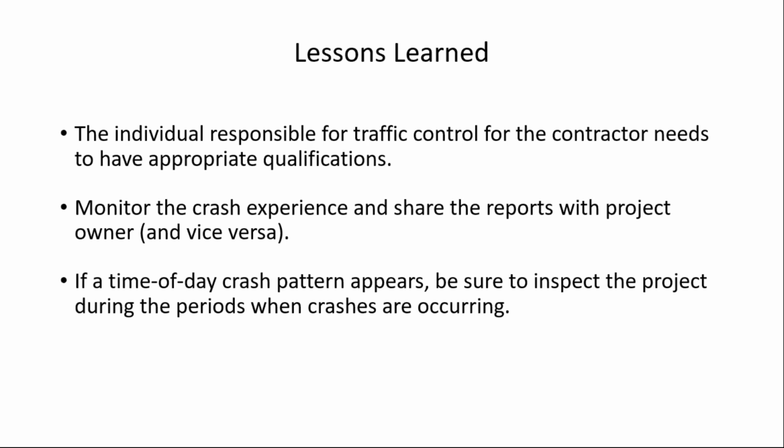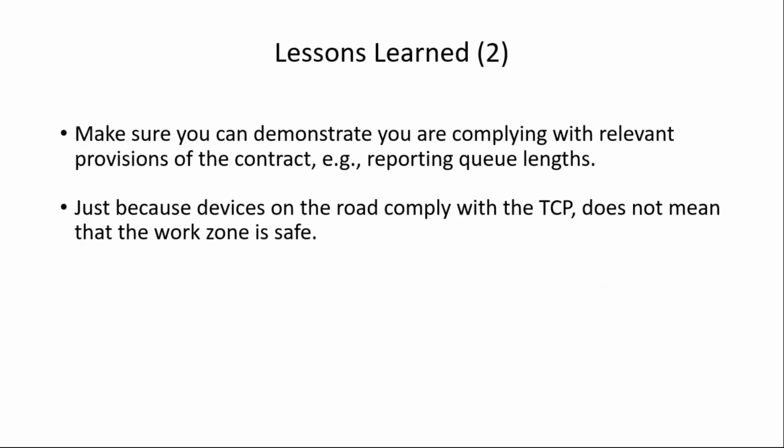And if there is a time of day crash pattern, be sure to inspect the project during that particular period of time, so you can try to get a feel for what the problems are. And make sure you can demonstrate you are complying with the provisions of the contract. And that gets into the documentation that we've talked about throughout all 4 sessions. And also, just because the devices comply with the traffic control plan doesn't mean the work zone is safe. There may be some underlying issues like there were here that need to be addressed.